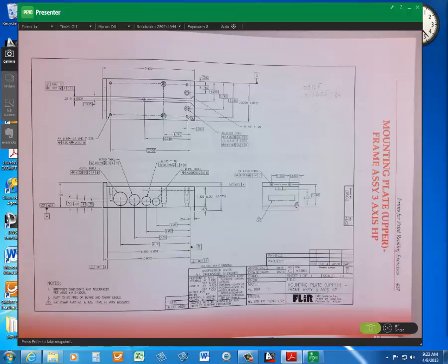Then as we produce different sizes up to LMC, we're allowed to increase. So in your little chart there, it first jumps 1/1000, then it jumps 2, then it jumps 1. So you just add it to it. Your next size would be 8/1000. Then for 0.190 it'd be 10 thousandths. Then for 0.191 it'd be 11 thousandths. All right, so with that in mind,